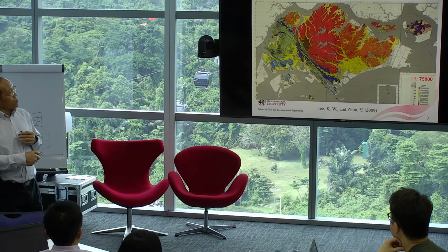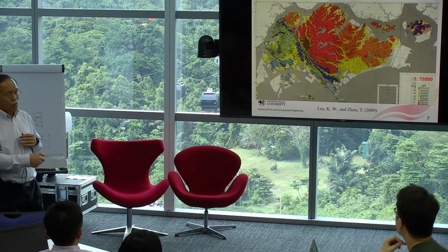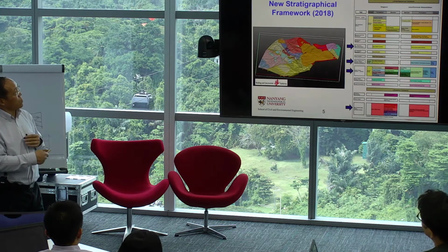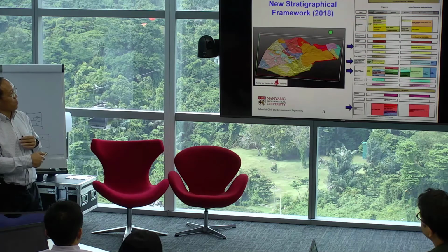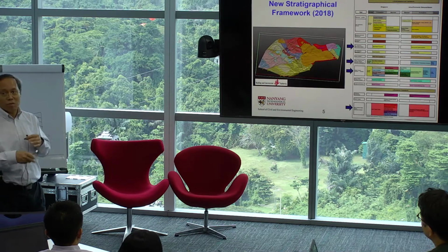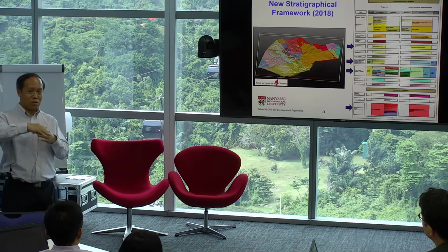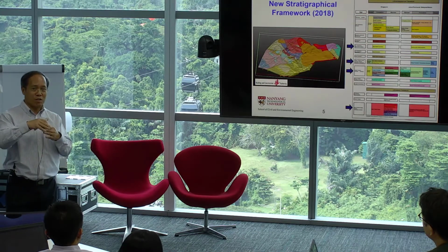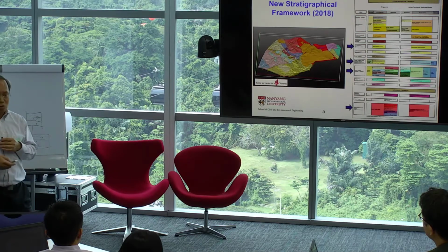We do have a 2D geological map showing over here. Basically, it tells you the geological distributions for the island. And recently, there's also a bedrock geological model constructed by BCA, collaborating with the British Geological Survey. This deals mainly with hard rocks. So we have a surface model, we have hard rock, but we don't have something in between. In fact, more than 90% of our construction is within the soil, the so-called subsoil. So that's why we need a subsoil model.